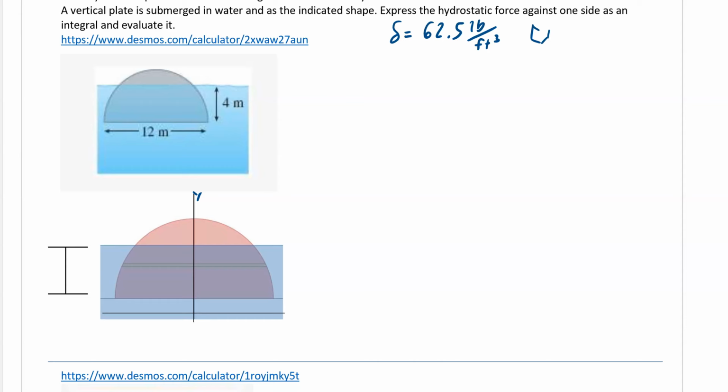What that meant was that we had this little cube, right? And it was 1 foot, and that means it weighed 62.5 pounds. So we need that same kind of unit, because then we took this and multiplied it by the volume to give us the entire force. And that gave us the pressure at the bottom by dividing by the area.